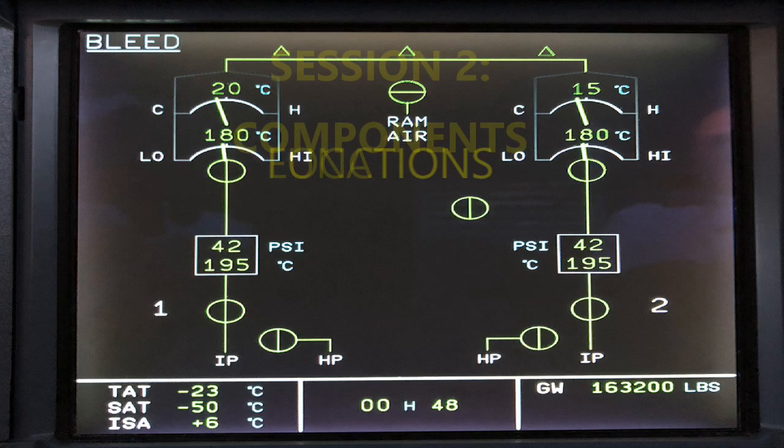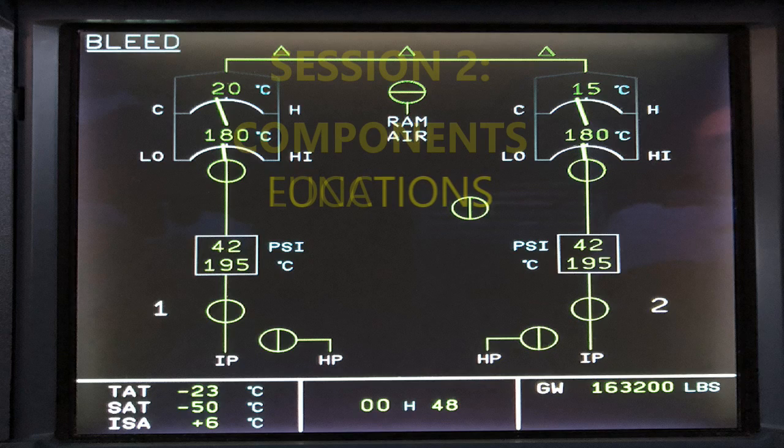And then you remember I mentioned that 392 degrees, it's basically monitoring that to make sure it's around that degrees Fahrenheit. And then you also have some safety devices involved here with the fan air valve. It has a test port, and that enables a test of that. There's also a manual override that can close the valve mechanically on the ground, just so you know.